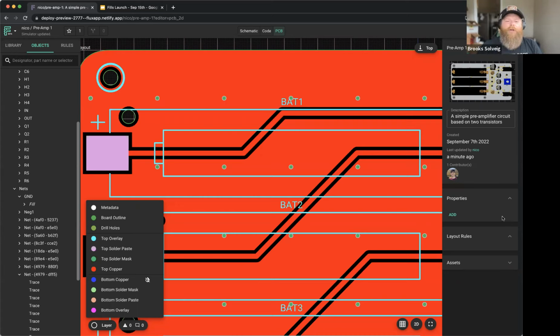Andrew, we'll look into this. But I'd love to know, just off the cuff, what those zones would be used for. What's the intent behind defining these zones? So if I had a board with general microprocessor stuff on one portion of the board, but then one portion was more RF-specific, where I want a tighter ground fill, or via spacing on the ground.